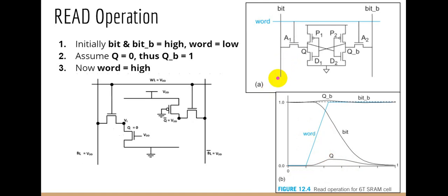If you connect a probe to the bit line and observe that your bit line becomes 0 volt, then you can say you successfully read 0 on the Q. Assume that previously Q was written to 1, and if you notice there is no voltage difference on your bit line in your probe, then you can say you successfully read the 1.